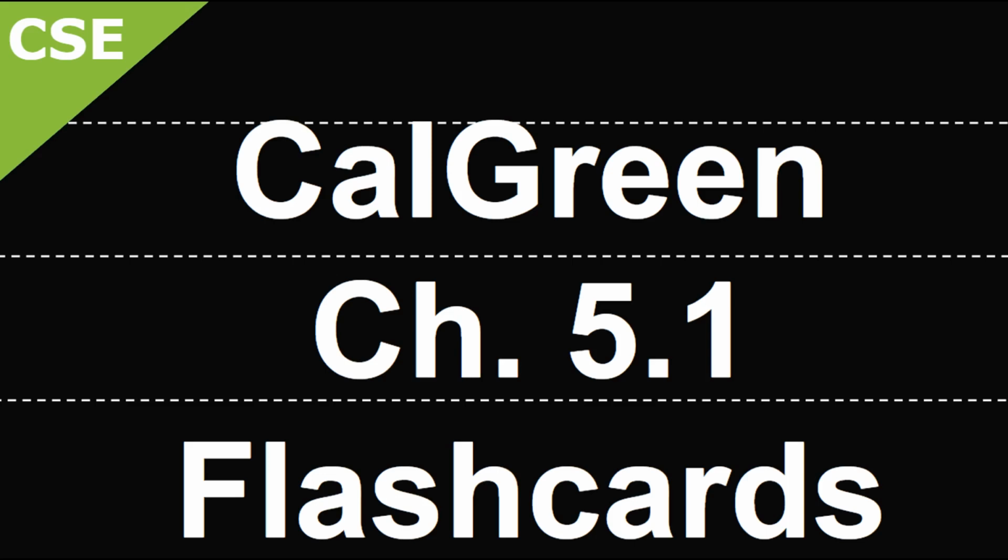If I decide to install 2 DCFC EVSEs using the allowed 5 EV-capable spaces to 1 DCFC ratio, then 2 DCFCs count towards 10 EV-capable spaces. The third EVSE will be a level 2 EVSE. Remember to satisfy the requirement of providing at least one level 2.